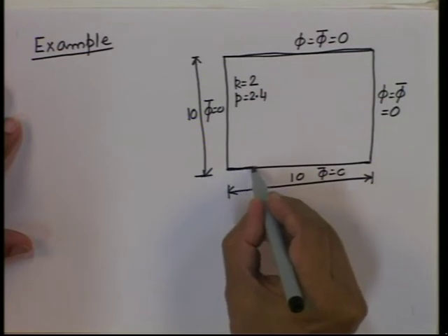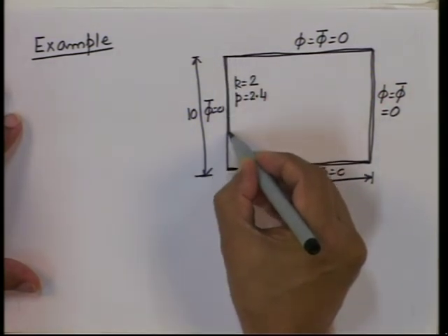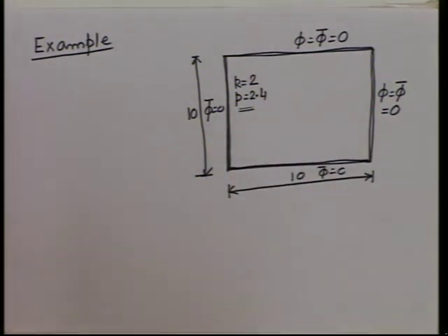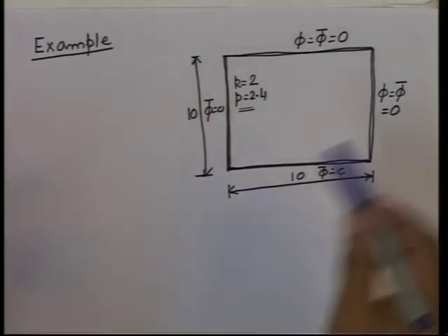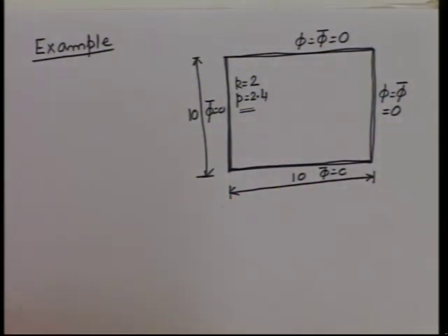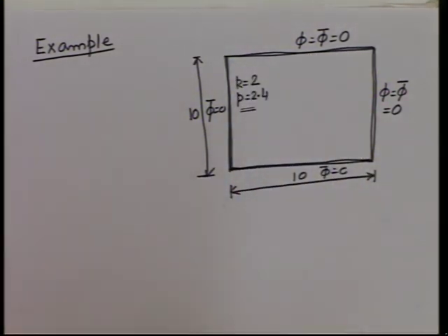That means on all 4 edges the temperature is maintained at 0. There is some internal heat generation through this plate, and we have to solve for the temperature distribution within this plate. Now, one option is blind discretization. Blind discretization should never be done. You have learnt about triangles, so let me divide it into some triangles. We start with 2 triangles, but that is not right in the beginning.